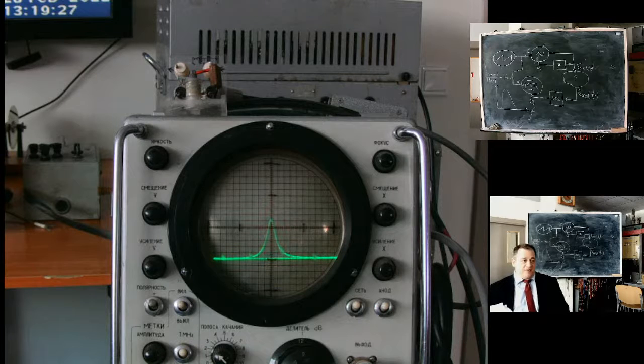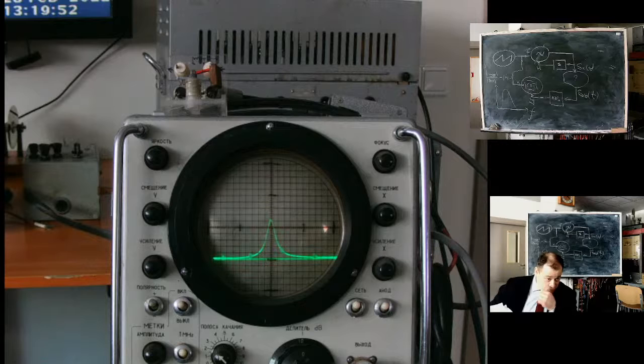The higher the frequency, see, at higher frequencies, the magnetic field pushes current lines out of the object. At low frequencies, current flows through all the conductive object. But at higher frequency, the closer the current will be to the surface. The magnetic field pushes current lines to the surface.